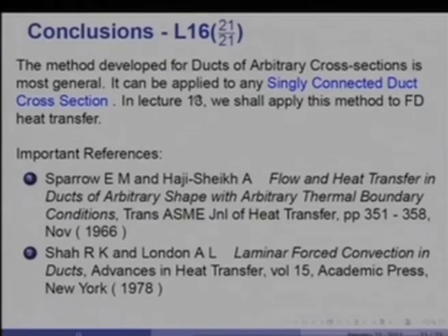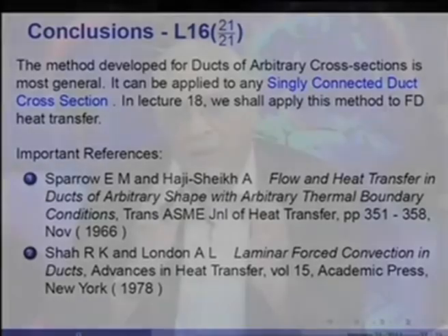So, as you can imagine, the method does not change with the duct shape. Unlike the Kantorovich method or the Fourier series methods and so on, where in each case you have to develop different functions to satisfy the boundary conditions, here you do not have to worry about that. You simply give the boundary point coordinates, and that is it. The method is general and can be applied.